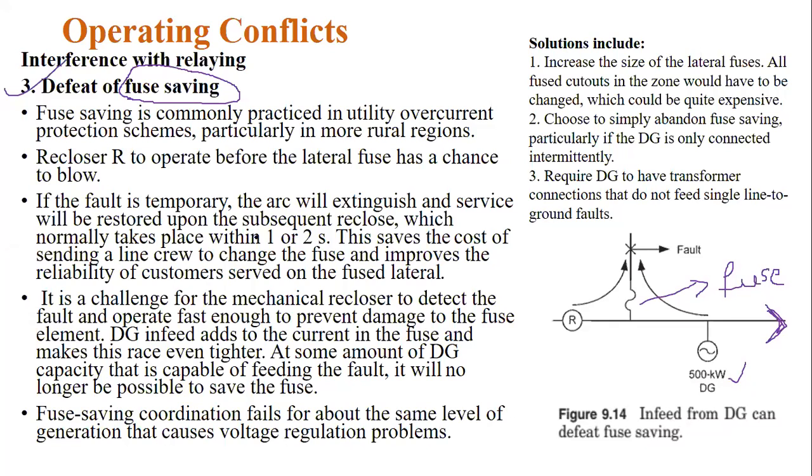So here our fundamental procedure, or our aim, is to save the fuse, even though there is a considerable amount of fault. At that time, first the recloser will open to clear the fault. You can design the system like that.